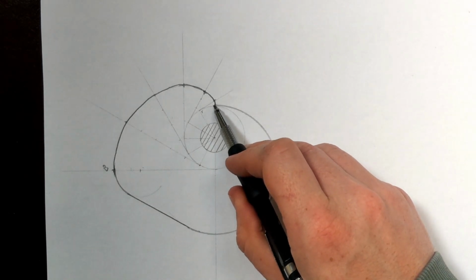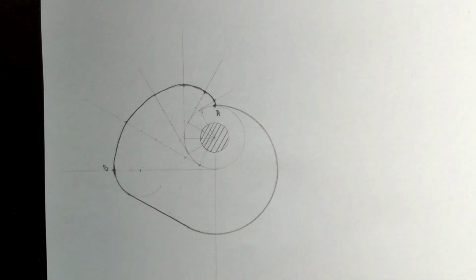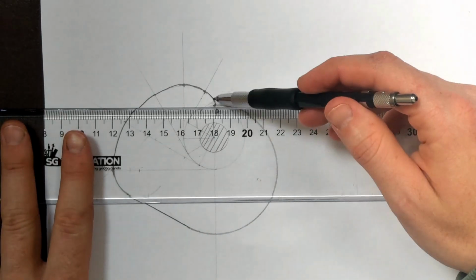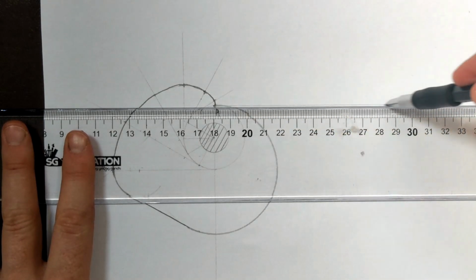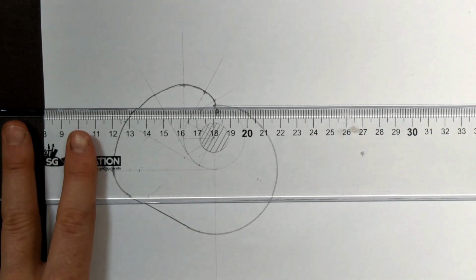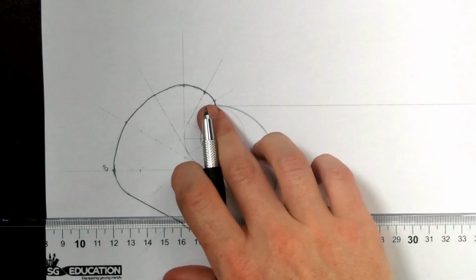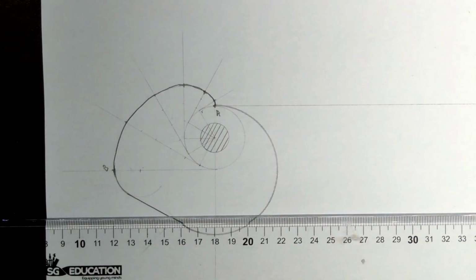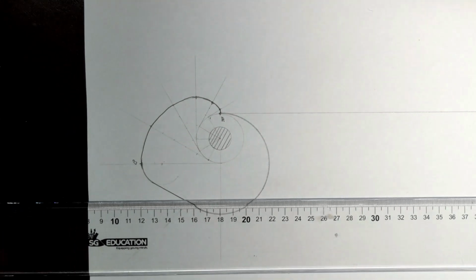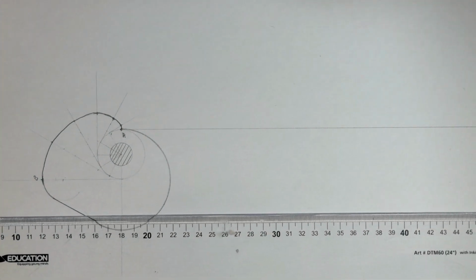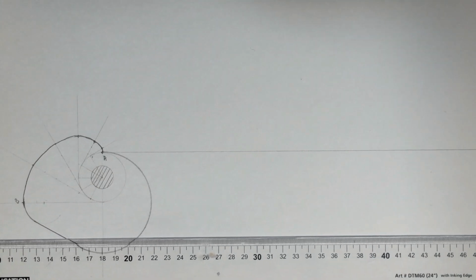That point there is always the nearest approach of the follower, and being the nearest approach of the follower means that it is the bottom of the displacement diagram. It's a knife edge follower as well, which means we'll actually be using these points. So that's the bottom of my diagram here now, and I'm going to zoom out because I need to use the rest of this sheet. I'll try and keep as much of it in there as I can.